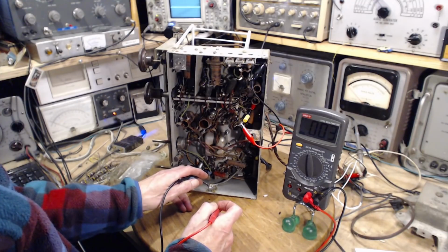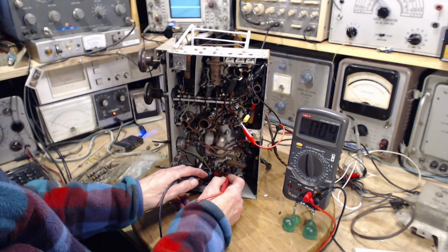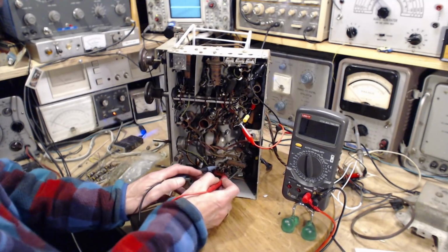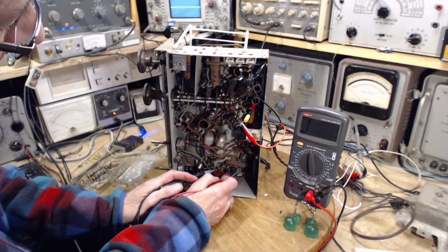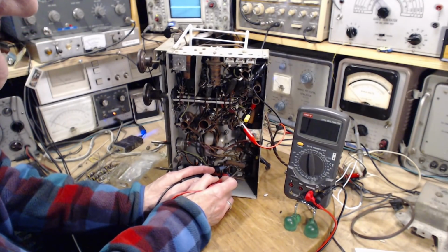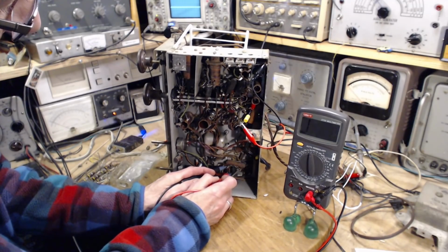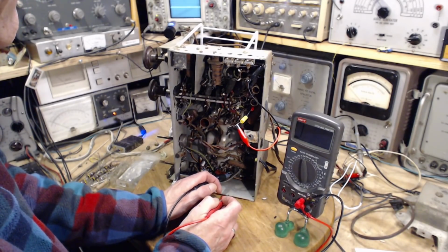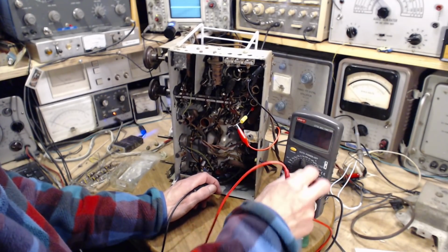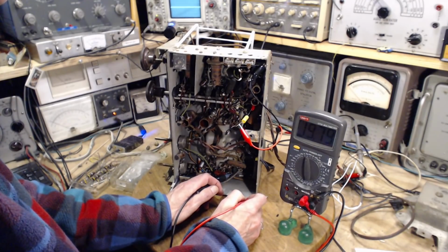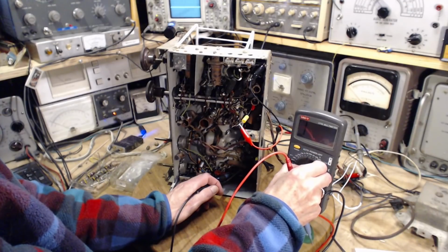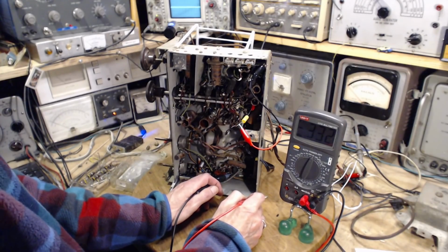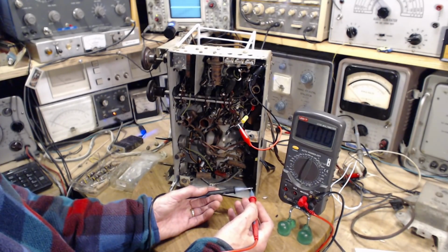Repeating what I did before. This is across one suspect capacitor. Across another suspect. This is the new one. And then this black guy here. Resistance to the chassis at this point. Ooh, we got something there. No, we didn't. 2 megohms. I had it on a bit of a low scale. Ah, negative, so there's a bit of voltage there.